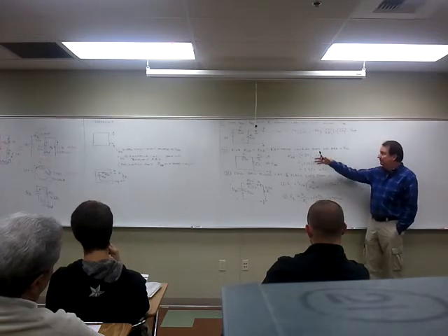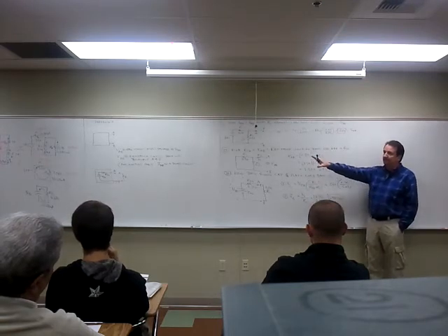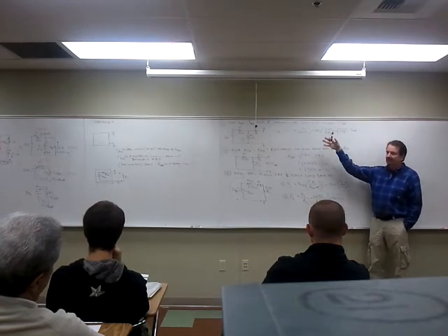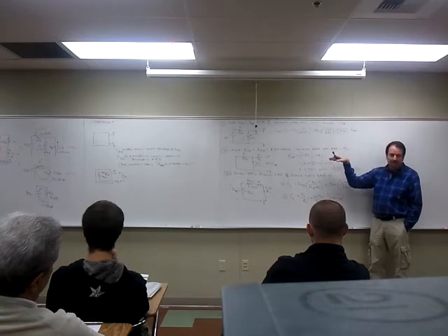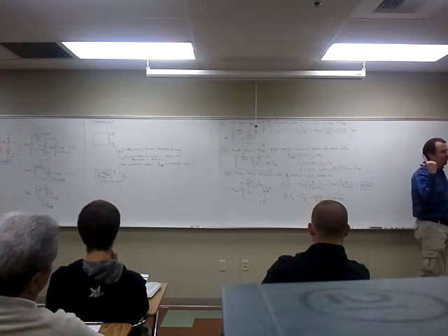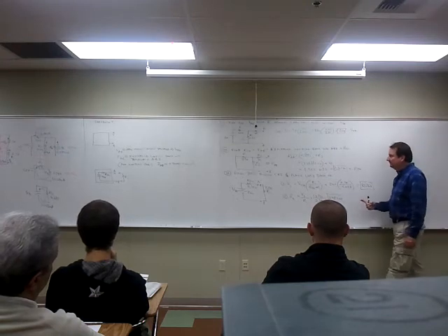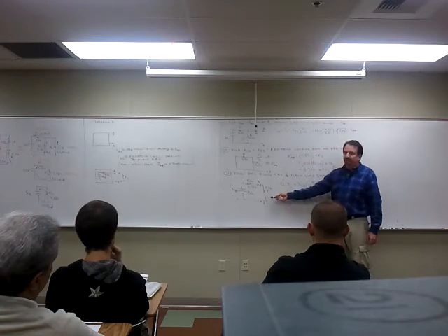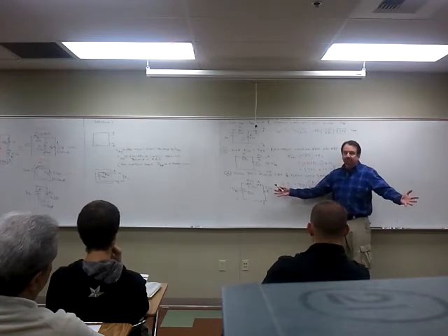Now maybe, depending on how complex the circuit is, this process might take many more steps. This happens to be an easy circuit. It only took small steps here. But what if finding the Thevenin equivalent took 30 steps, but you only do it once? Once you have the equivalent circuit, it's tiny. Now in this tiny circuit, when I change this resistor, it only takes 2 steps to get to a solution.